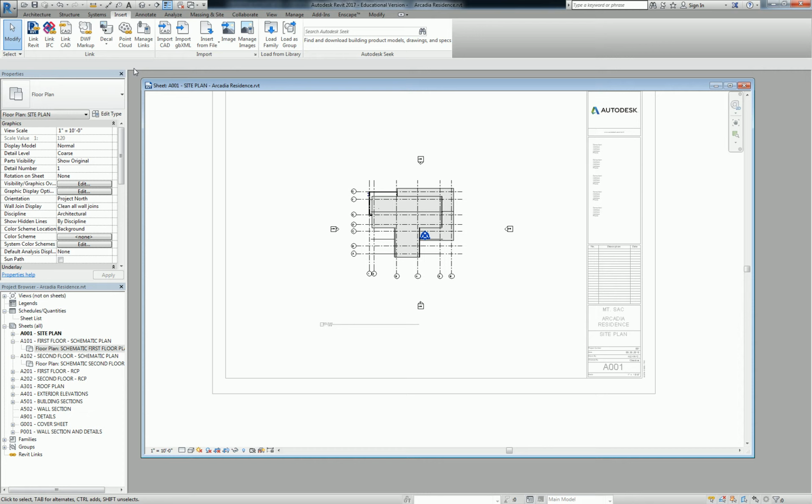What we're doing is we're going to link the CAD file because we're going to emulate this process where the civil engineer hands you the CAD file and you say, okay, I put it behind my building and I'm going to use that to coordinate the design of the site. So if anything changes, I can refresh the file and it'll show those updates. Does that make sense? Yes, okay, let's proceed. So we're going to go to link CAD,